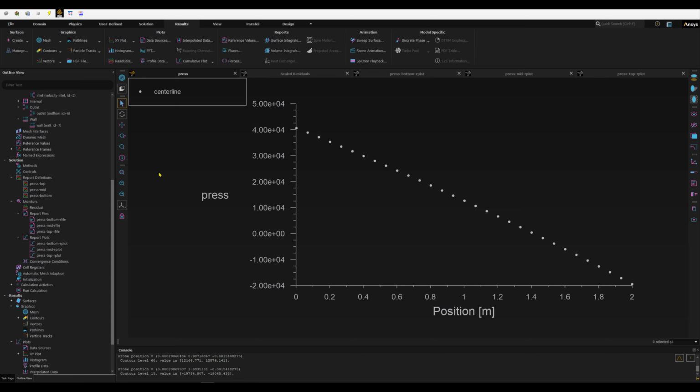So okay, and that completes our simulation of flow around the curved channel. We started from geometry and meshing, set up the boundary conditions, and ran the case in Fluent. Finally, we compared these CFD results with the analytical solution, and as we saw, the pressure values matched quite well with only small differences. I hope this lesson helped you understand how to approach curved flow problems and how to use Fluent effectively for this type of analysis.